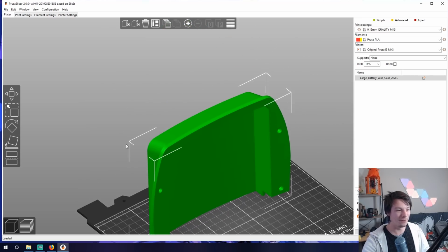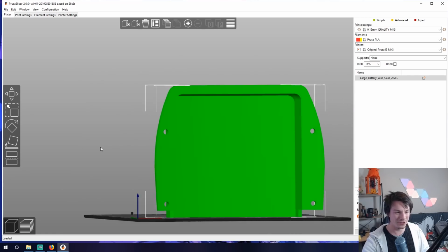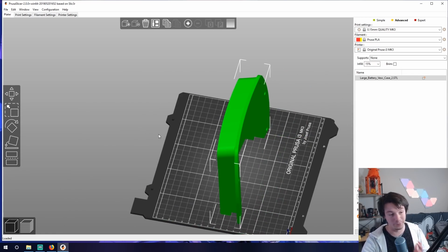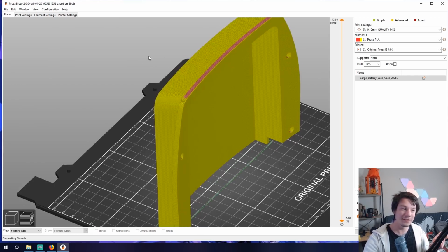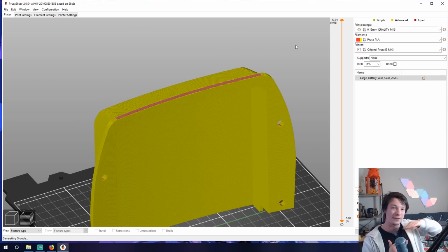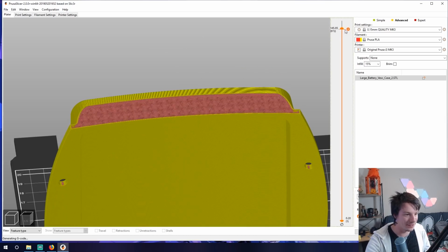Now that top overhang, if I try to look at it here, it might bridge, and I'll do some settings, but it might not be that clear. So we're going to need support material for this model, at least for the bottom detail. So let me just slice it to get a good idea of where the plastic's going to end up, to see if I can get away with bridging or not. Bridging, if you're not familiar with, will just go across thin air without support materials. But there is certainly limitations to that. So let's have a look here.